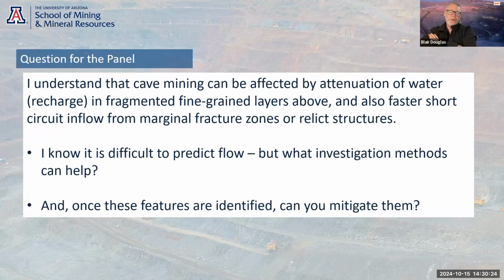I was just going to make a bit of a statement about it being very difficult for caves to predict inflows, but most of the time, my experience would be it's surface water related contributions that you need to understand. So you've got a water balance issue, trying to understand the propagation of structures and where they may penetrate to the surface and how it connects with surface water becomes the real key here. Notwithstanding, when you understand the surface water contributions, there's also the groundwater elements, which can be quite significant, particularly in sub-level block caves where you haven't propagated to the surface.